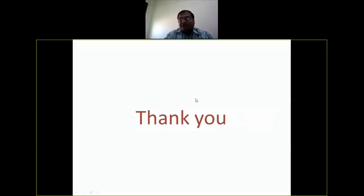So today we discussed some definitions. In leveling operation, what is backsight, what is foresight, what is intermediate sight, what are change points, what is station, what is benchmark, what is datum surface, and then we discussed two very important methods: HI method and rise and fall method, and how to enter the readings in tabular form, then how to calculate the height of the instrument in the HI method, and how to calculate rise and fall, and finally how to calculate the RL of all these station points. And this is very important because this is a calculative portion which is included in the GTU syllabus. So if you do this example correctly, then definitely you can score good marks in this particular subject.